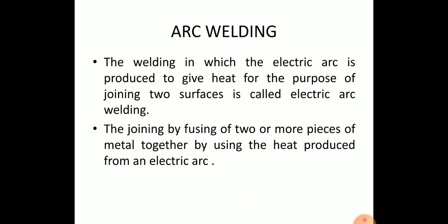Arc welding is a group of welding processes wherein heating is produced with an electric arc, mostly without the application of pressure and with or without the use of filler metal, depending upon the base plate thickness. Various arc welding processes are: carbon arc welding, flux shielded metal arc welding, TIG welding, MIG welding, submerged arc welding, electroslag welding, electrogas welding, and plasma arc welding.